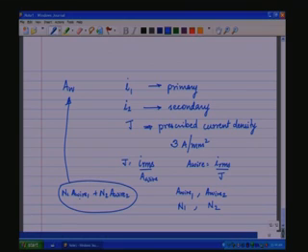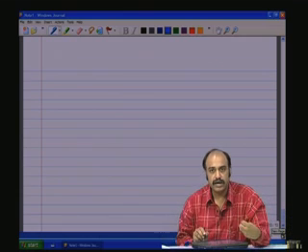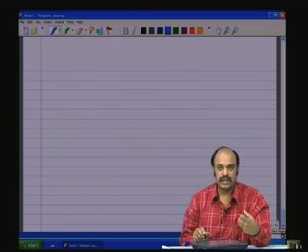Now, A wire is dependent on the RMS value of the currents. So, the current carrying capability is decided by AW. The voltage capability is decided by AC or the cross sectional area of the core.